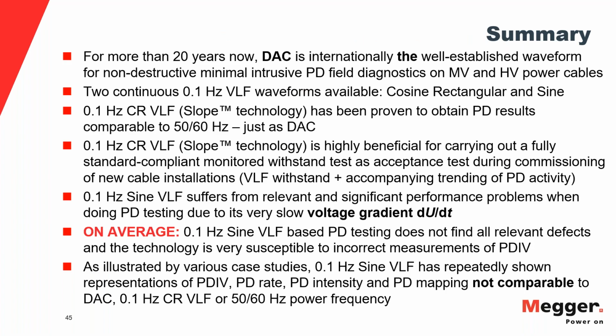So then as a summary, for the last 20 years, damped AC is pretty much the technology. On average, the sinusoidal test sets are not recommended for PD testing because of these issues with the layered interfaces, with the joints and the end terminations due to the insufficient gradient, the dV/dt. Damped AC is established. Slope is used for monitored withstand testing, and those technologies are comparable to a stiff 60 Hertz test set.